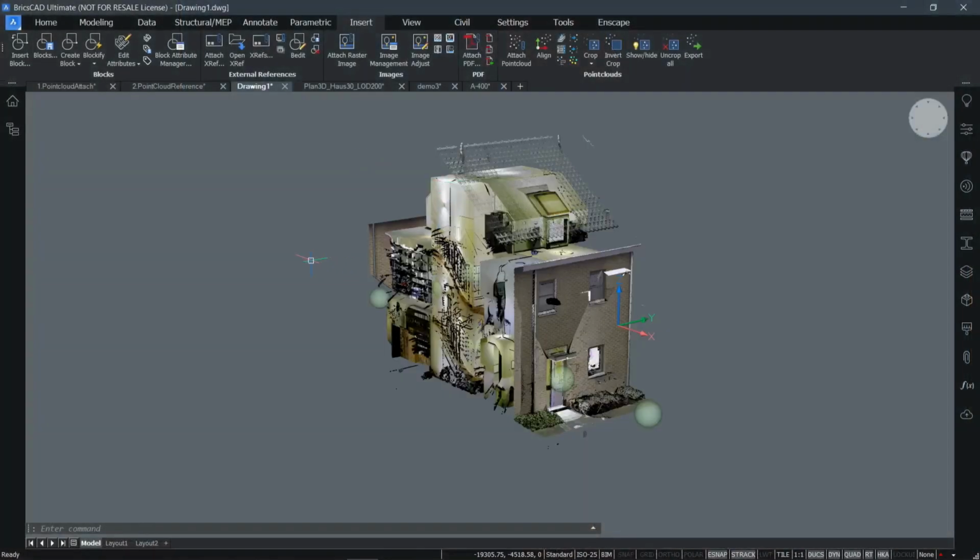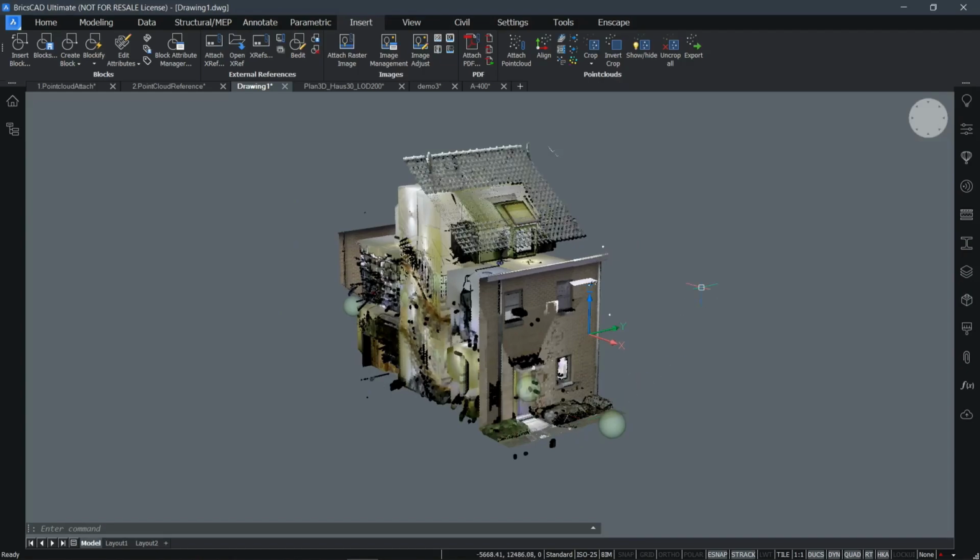So of course, if you have a bigger point cloud with multiple floors like this one, or I have another example of a house here where I have different floors, I can of course use the section command to do that, but in BIM we also have an automatic floor detect command for that, so you don't have to manually add this yourself in your point cloud.